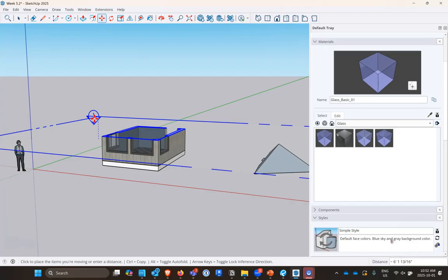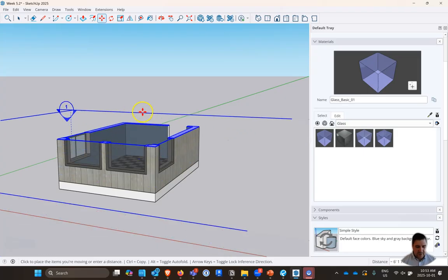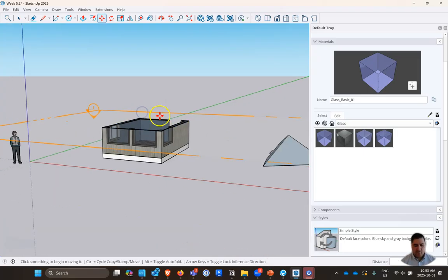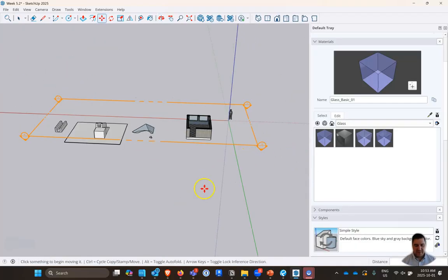And so when you're looking at a floor plan, you're going to see desks. You maybe see the bottom edge of this TV. You see the bottom edge of these. You're not going to, however, see fans and lights up there. You will probably see light switches, door handles, that kind of stuff. And so 4 feet is a good metric to think about where you cut a floor plan. And so when we do this, we can artificially try to find that 4 foot mark. And this allows us to see in the building like this.